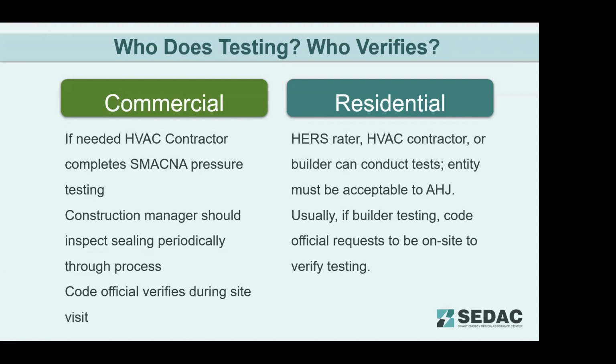So I highly recommend, one of the mistakes I see in the field is they learn they need to do the duct pressure test too late in the game, such as when drywall's already up. And so they're nearly into construction, and then we come in, and if the duct pressure test doesn't pass right away, it needs to be sealed more. And getting that done after drywall is much, much more difficult than doing it pre-drywall. If you're doing the test at rough-in, where you can see all the ducts and get to them all, it is much easier to make sure that system is going to pass that test.